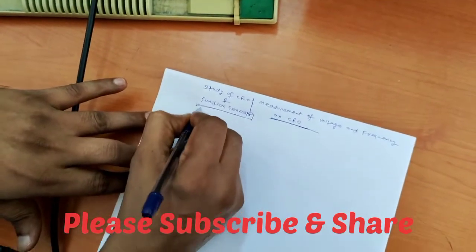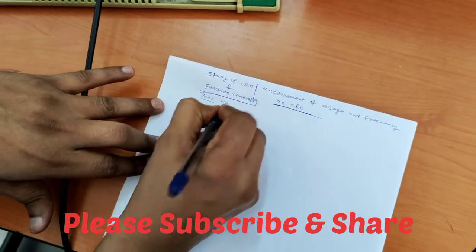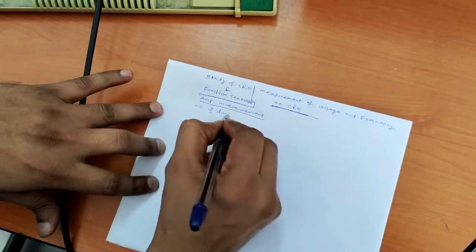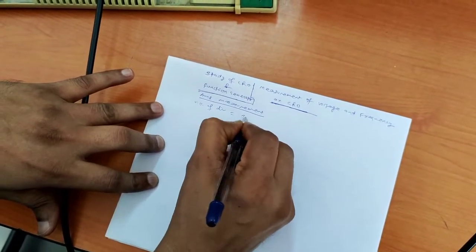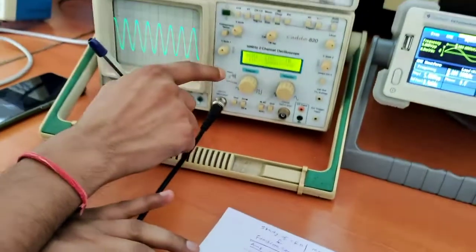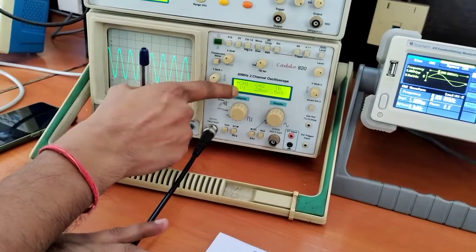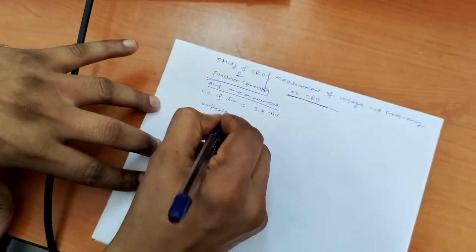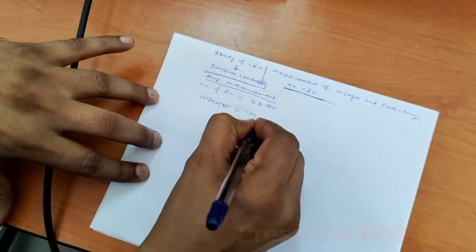This is for amplitude measurement. The number of divisions we have calculated was 3.8 divisions. Now we have to check the voltage per division. The voltage per division is now set at 1 volt. So we can write it: voltage per division is equal to 1 volt per division.